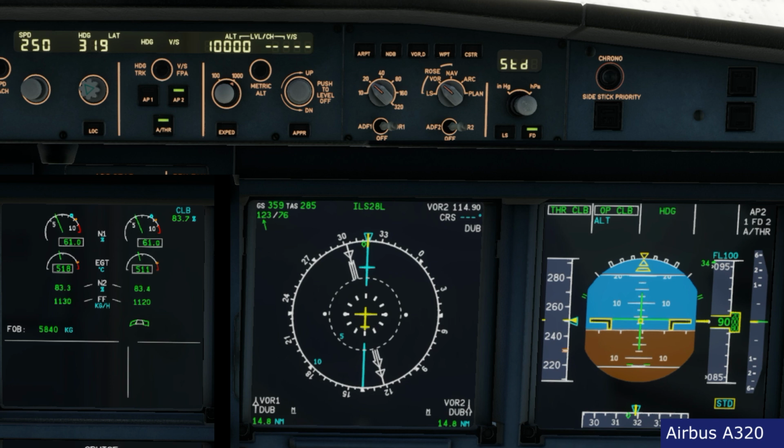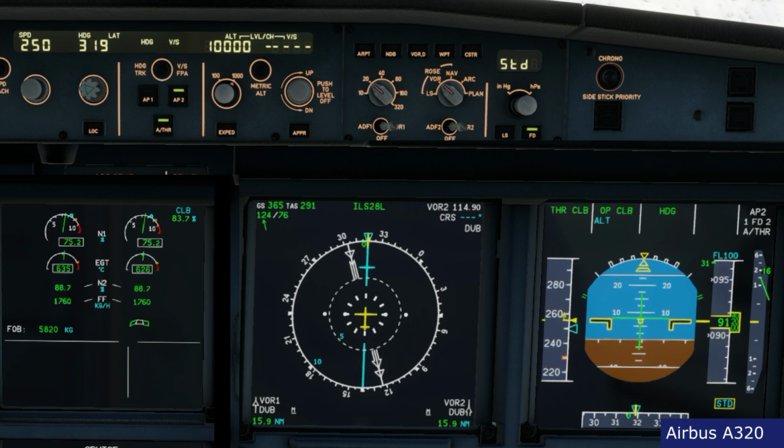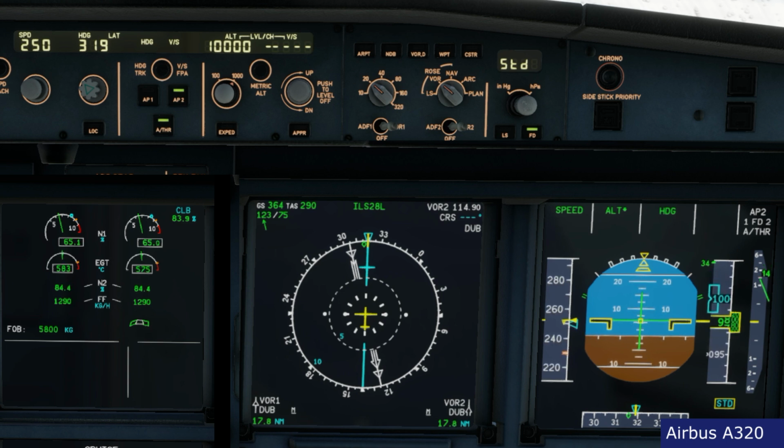In this case, the altitude is higher, so the system is going thrust climb, as you can see on the fly mode annunciator. I see open climb, and on the Airbus I see that altitude is blue, altitude is armed. On the 737, of course, this altitude blue is not shown because the altitude is always armed, but is not shown. Alt star is the acquisition phase of the altitude, where we smoothly start reducing the rate, and as soon as I get alt star, I also get the thrust mode going back into the speed mode.